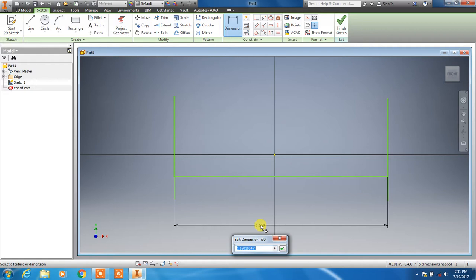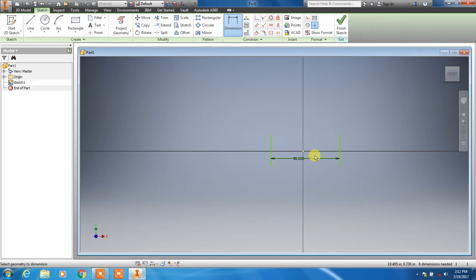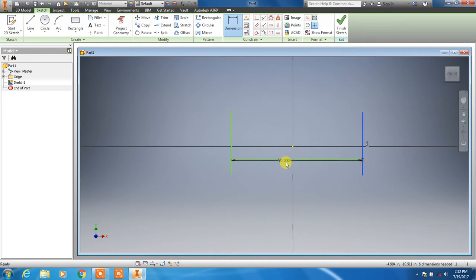Well, I don't want it to be a complete 96 inches because I want the table legs to be recessed from the edge about 3 inches on both ends. And I'm using 3-inch square tubing for the legs, so we'll make a little bit of a compensation there. We're going to assign this value at 90 inches. That will allow me 3 inches at both ends of the table. Now, I can come in and change this dimension at any time if I choose to. I'll show you how to do that here in just a minute.